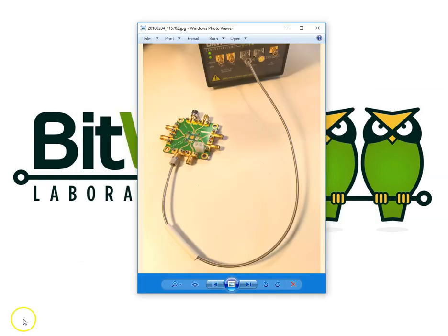In today's demonstration, I'm going to make simple measurements of a device under test. This is a synthetic example that I just created from something in my lab. We will send the pulse out single-ended, thereby terminating the other differential output, and bring that signal through a small transmission line, an exposed wire, and another transmission line back into a termination, just so that we can see and experiment with the kinds of impedance mismatches we might see in a real circuit.